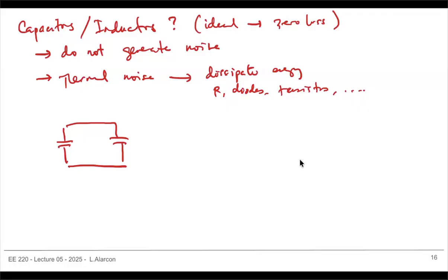As soon as this generates noise, it generates energy, it starts to charge up the cap, and since it does not have any resistance, it's continuously charging up that cap. So you violate thermodynamics, because now it seems I have an infinite source of energy. As soon as I get energy, it gets stored. Hopefully we remember the stored energy in a cap is 1/2 CV squared.